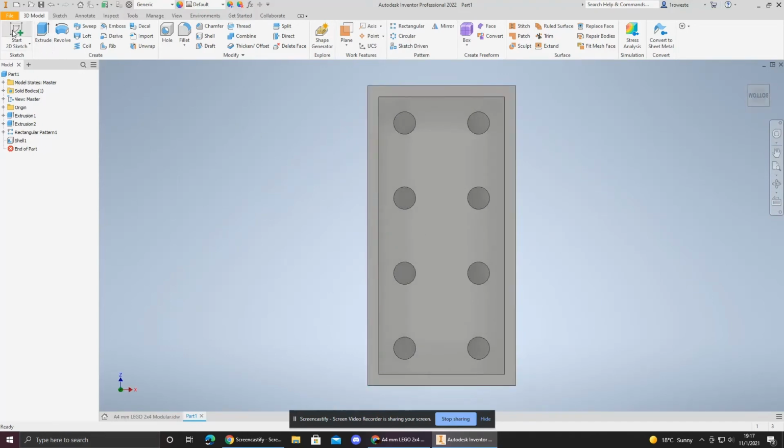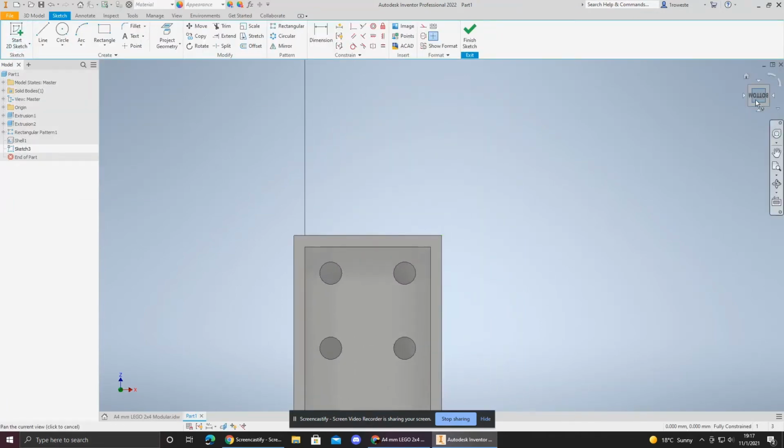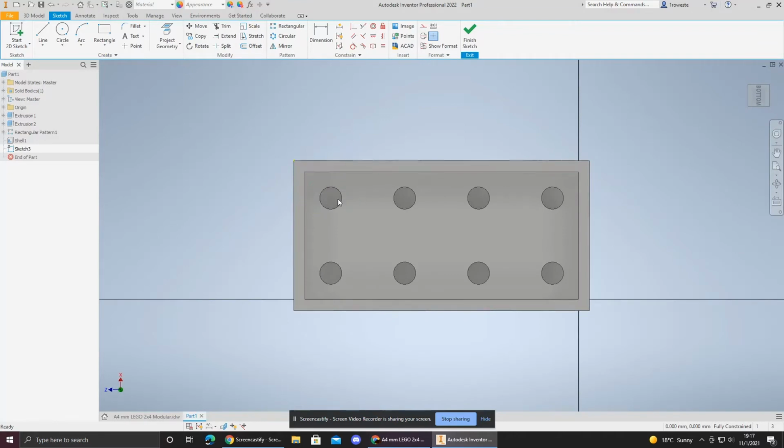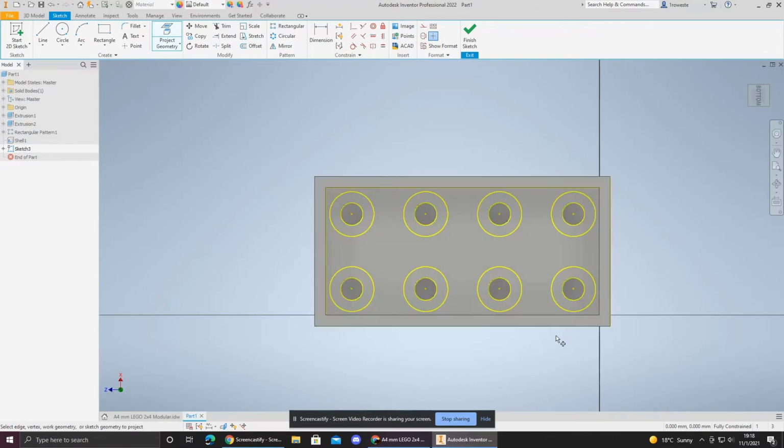In order to create these extrusions, we will once again need to start a new 2D sketch. Beginning the sketch, and orienting to your preferred angle, we may now use what is called the Project Geometry tool. By pressing Project Geometry, you can select geometries that would not otherwise be visible. I have repeatedly done this for the sake of accentuating my point, however, doing it this many times is not necessary. In essence, this will highlight borders which otherwise might not be visible.